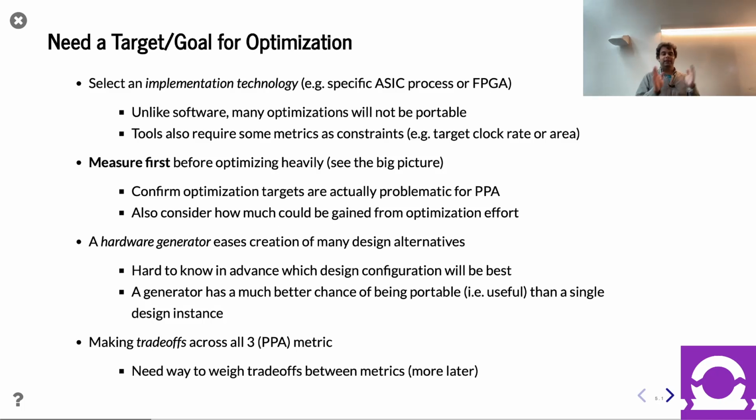The other point is that there are some Chisel designs out there where the person realized there's an opportunity to optimize, and leaving it to the end for the physical design CAD tools, they might miss some opportunities. And so as a result, things like Rocket Chip internally actually had an implementation of Quine-McCluskey, a classic optimization algorithm, to run on the decoder, to actually optimize the decoder for you.